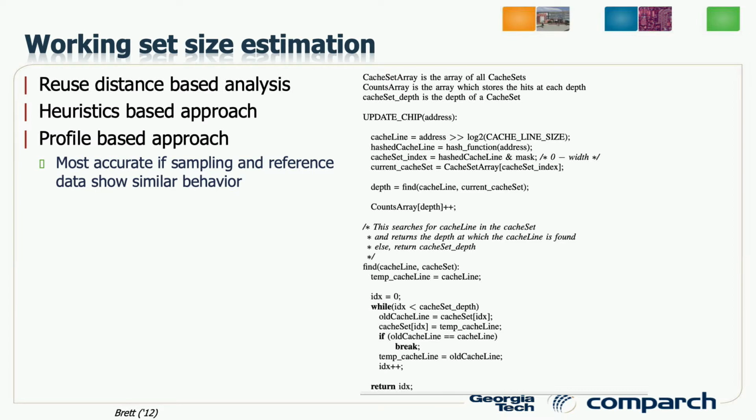One of the techniques that we have proposed was the chip profilers, where by only profiling one set of the caches, with different workings at different set associativities, we can estimate the required cache sizes. It also gives some estimation of the cache hit rate at different cache sizes. So in this method, we just do one-time profiling and get different cache hit rates for the different cache sizes.